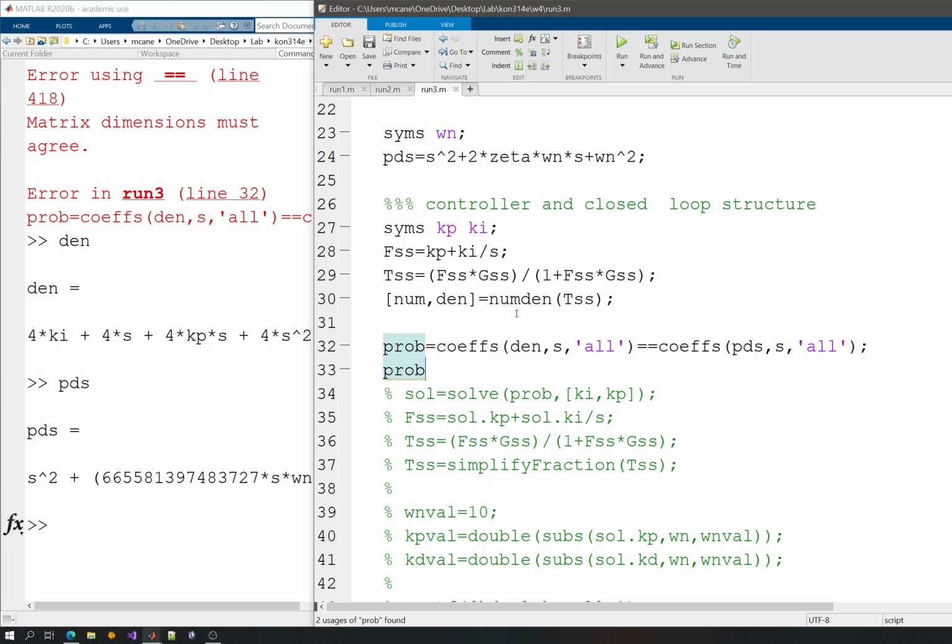So basically, what we are trying to say is that we have too many poles, but we are choosing only 2 of them, and if they are slow enough, which means that they are dominant, then we can adjust the closed loop time domain properties.